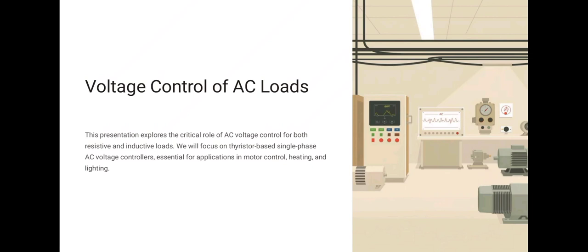Voltage control of AC loads. This presentation explores the critical role of AC voltage control for both resistive and inductive loads. We will focus on thyristor based single phase AC voltage controllers essential for applications in motor control, heating and lighting.